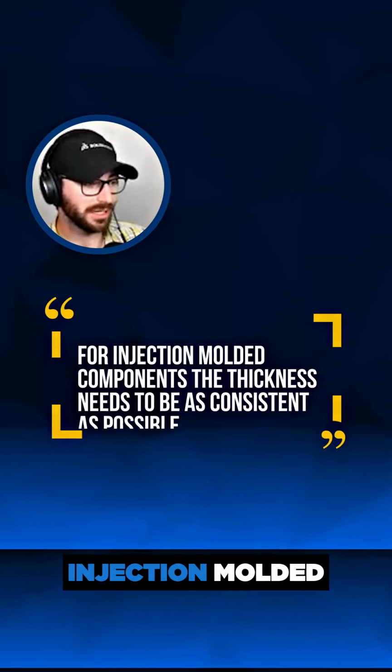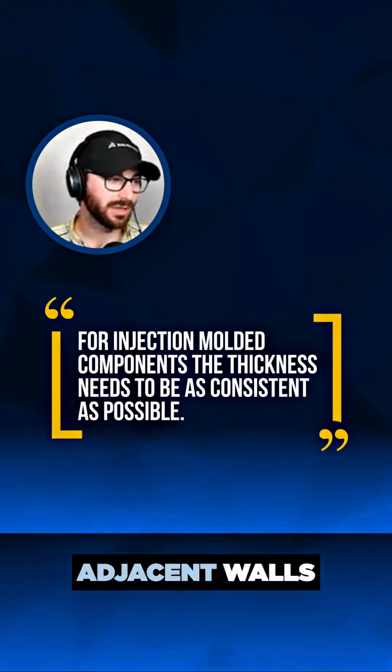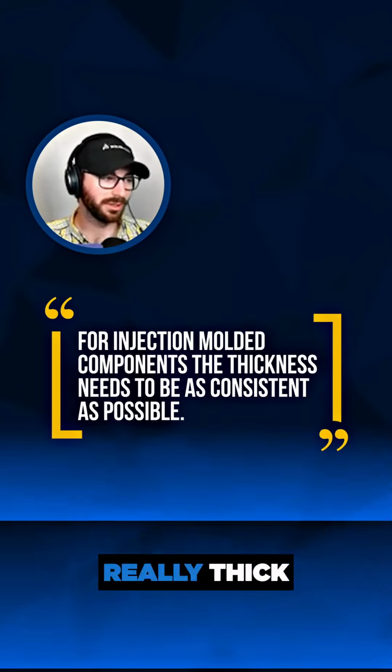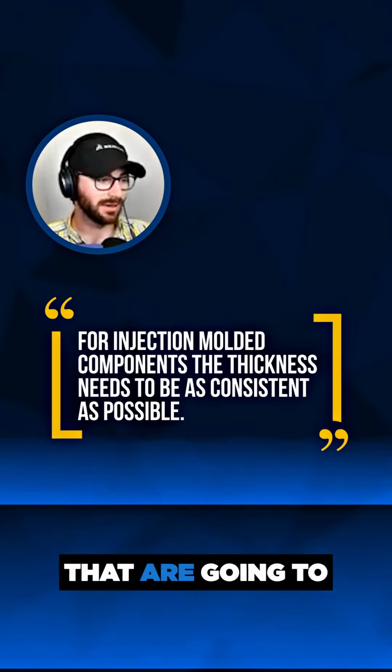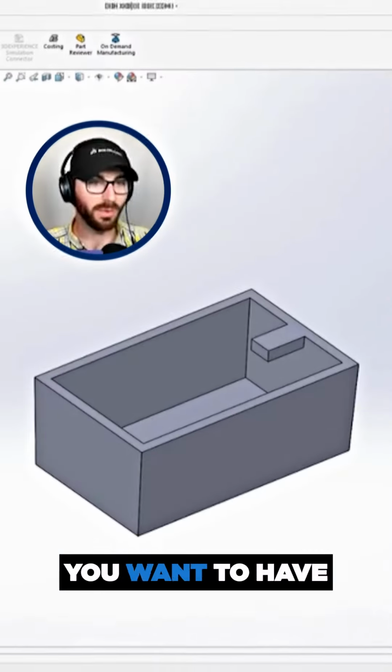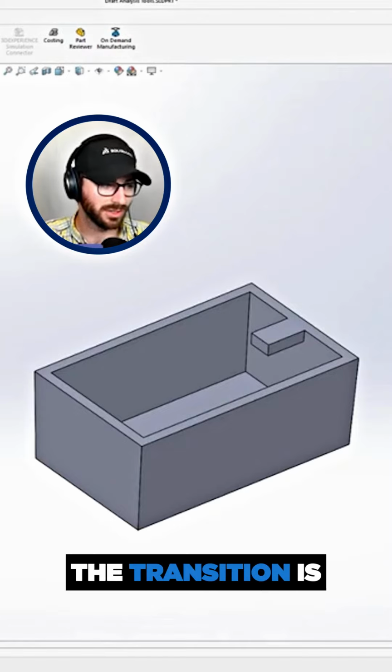Generally, when it comes to injection molded components, you want the thickness to be as consistent as possible, especially on adjacent walls. You don't want to go from a really thin wall to a really thick wall, or else you're going to have a lot of manufacturing defects, warpage, things like that that are going to make the product not look so nice. You want to have the same thickness, and if not the same thickness, you want to make sure that the transition is very gradual.